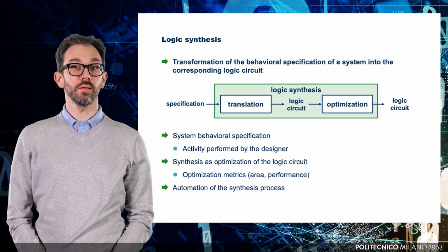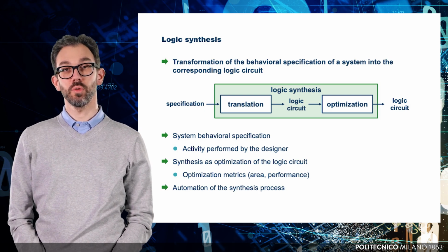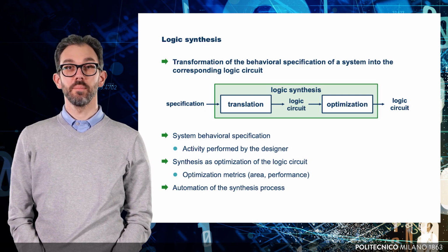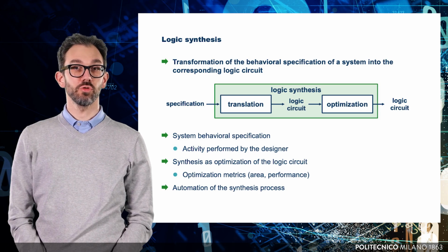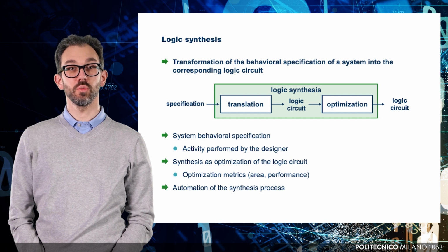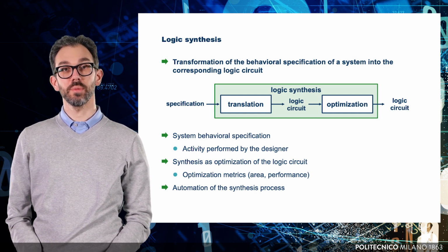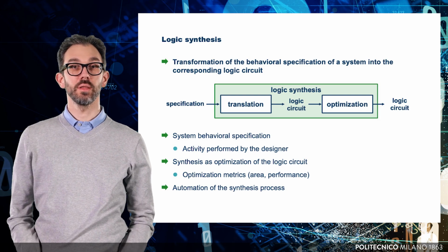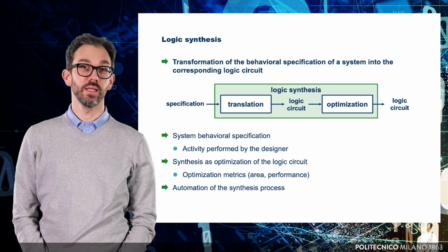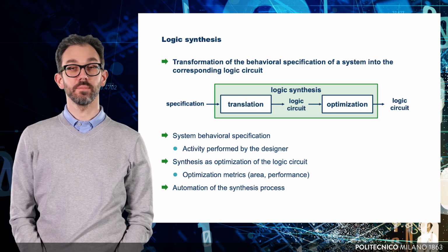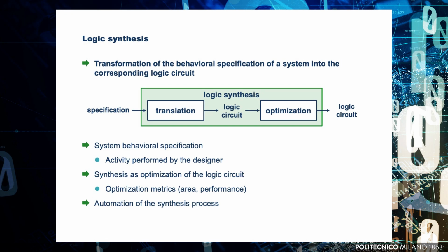For this reason, the synthesis process also performs an optimization of the circuit based on one or more metrics used to estimate the characteristics of the system with respect to the non-functional requirements under consideration. This course series will mainly focus on optimizing the size of the logic circuit in terms of the number of logic gates required for its implementation. In some cases, we will also analyze system performance, that is, the time required for a circuit to produce an output in response to each input stimulus.